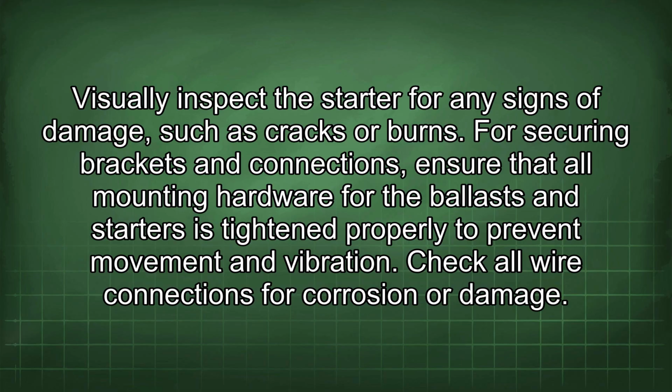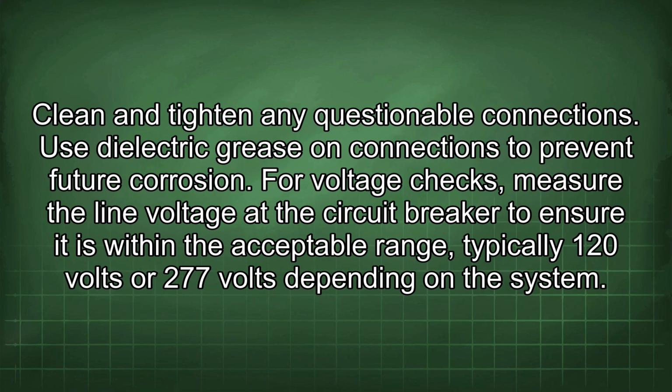For securing brackets and connections, ensure that all mounting hardware for the ballasts and starters is tightened properly to prevent movement and vibration. Check all wire connections for corrosion or damage. Clean and tighten any questionable connections. Use dielectric grease on connections to prevent future corrosion.